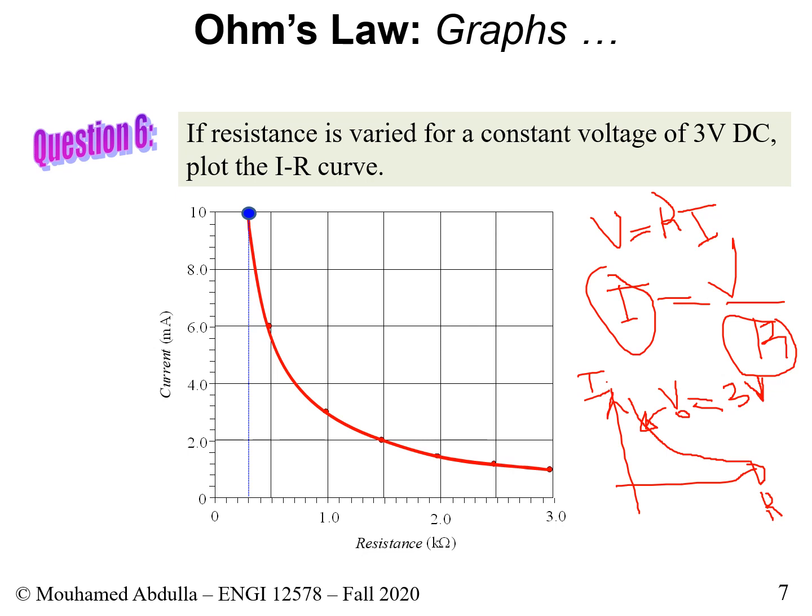So, for example, if we look precisely at, for instance, this is 1 kilo ohm, this is 0.5 kilo ohm, and this would be 0.3 kilo ohm, or if you will, 300 ohms. So at 300 ohms, we get a current of 10 milliamp. Okay, and here we have another point that we could also get, because these are points on the plot. At 3 kilo ohm, I guess, we get 1 milliamp.